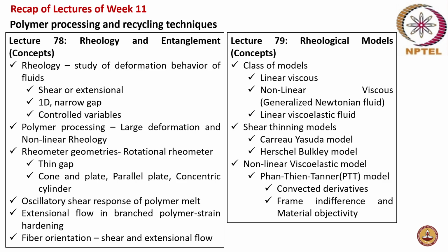Generally, these rheological experiments are done for simplicity in one dimension, and also narrow gaps are used and different control variables. Either it can be a stress controlled experiment, strain control, oscillatory experiment, steady shear experiment. But polymer processing involves large deformation and non-linear rheology.